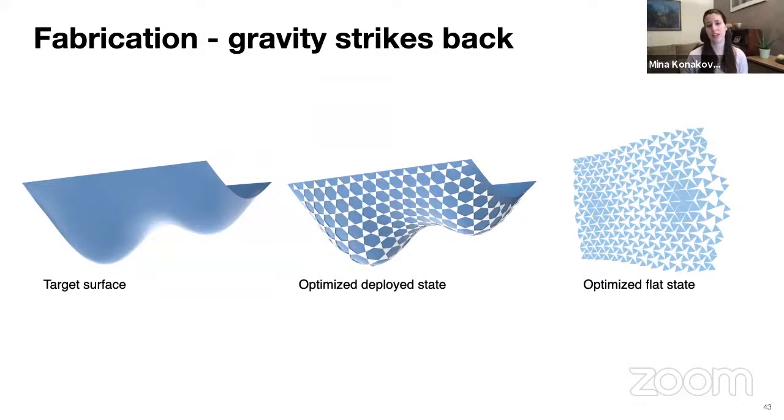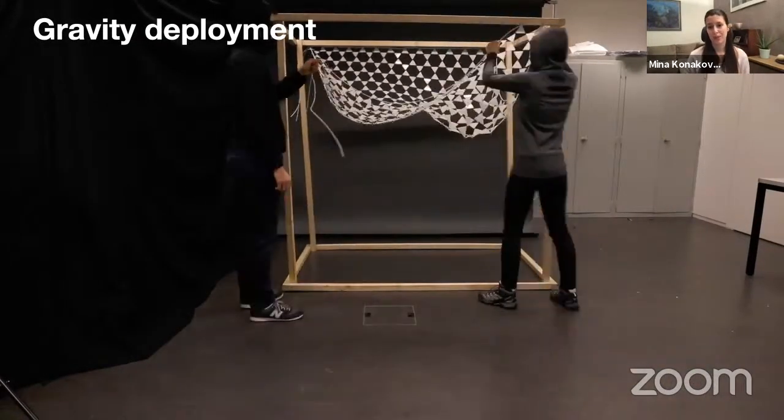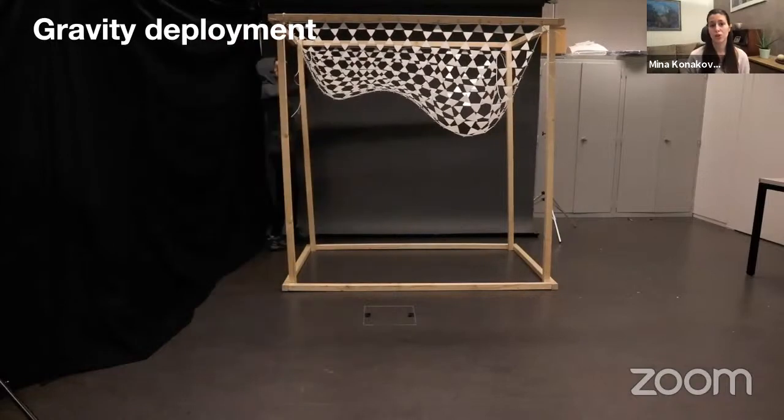I also mentioned gravity as a deployment mechanism, so I'll briefly show an example of that. And again, we can only do surfaces of positive mean curvature, but can allow for unintuitive negative Gaussian curvature like the saddle point in the middle. We take the programmable linkage and just need to hang it, and it will go to a prescribed shape. And you can see that thanks to our optimization approach, we are able to create a linkage that can keep this unintuitive saddle point in the middle part of the linkage.